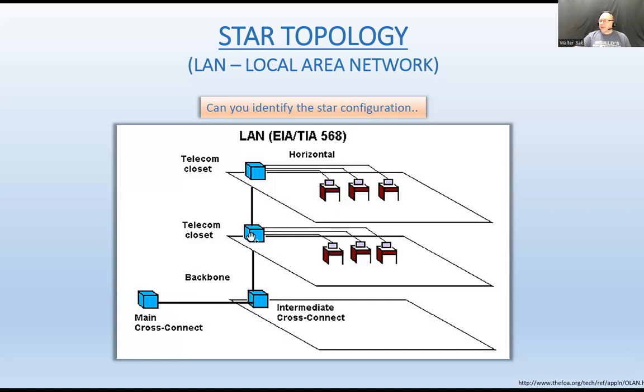Now, from the risers, you're going to have individual field wiring that goes to each individual floor. So here, all the connections that are connecting to this distribution frame, which is part of the riser, are considered horizontal runs. Okay. So here will be horizontal runs that have to do with this floor. Here will be horizontal runs that have to do with this floor, and so on.